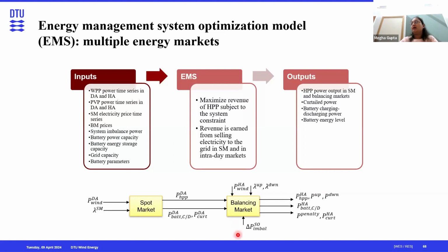And then this system imbalance, this is at the plant level, right? Those are the wind forecast errors. But at the same time, if I'm connected with a system, then the system can also have some imbalance because it will be an aggregation of the whole area. So our up or down regulation services will depend upon the system level, not on what we have as a plant.